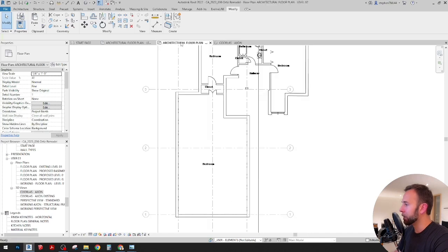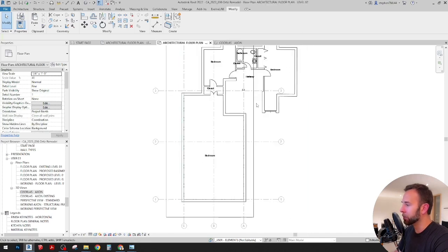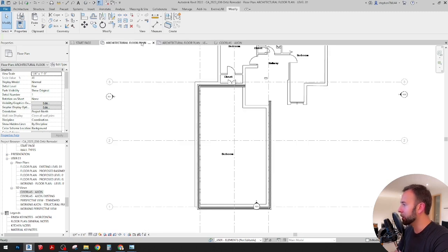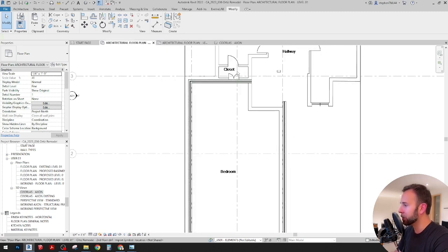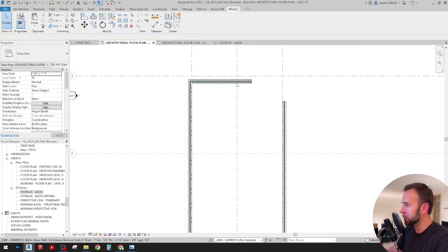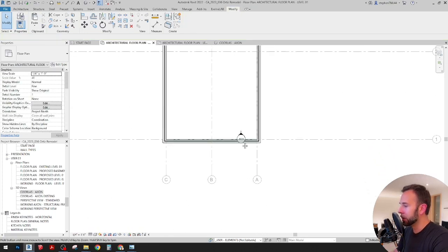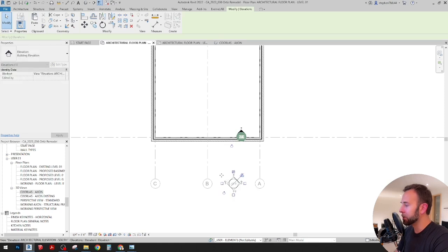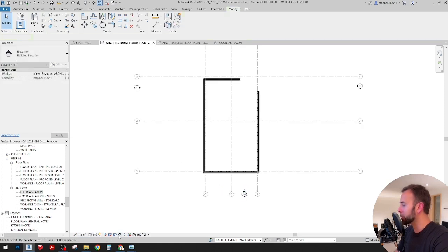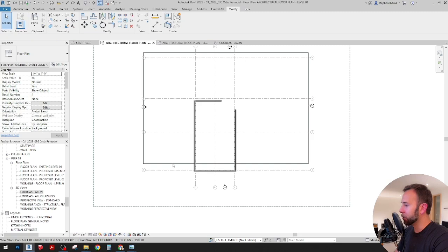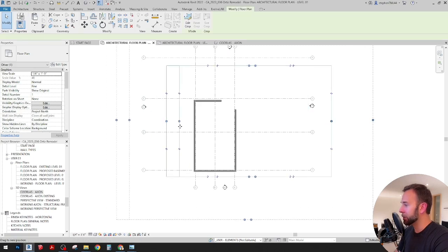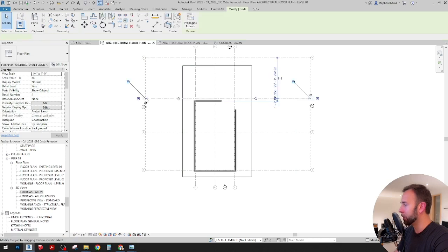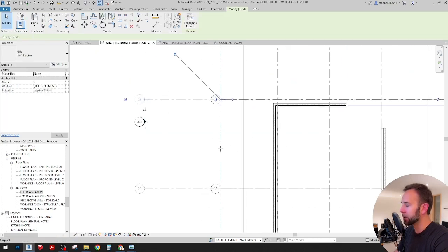So jumping back in. When you come back to your level 2, if you've reset those, now those are going to be below your visibility plane in some cases, but the level 1 still shows it down here. And this is now off, so we'll just erase that. Like I said at the beginning, I have pre-set up templates. So elevation views, all these sorts of things are pre-set up and placed on sheets just to help move things along quicker when developing concept designs, things of that nature.